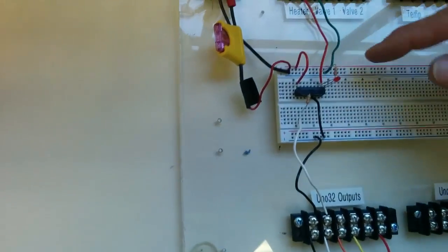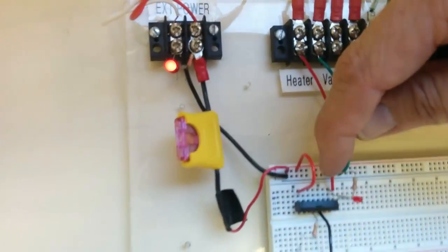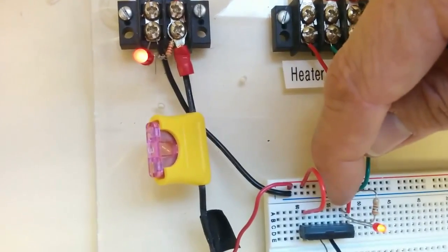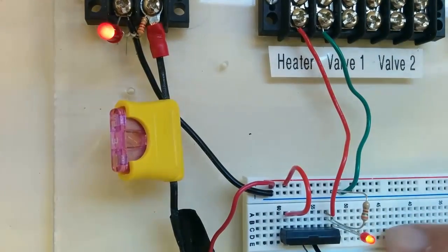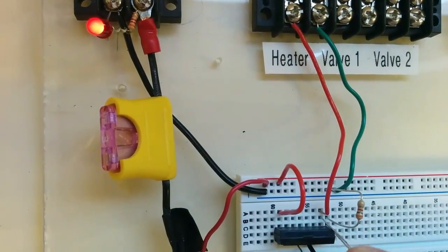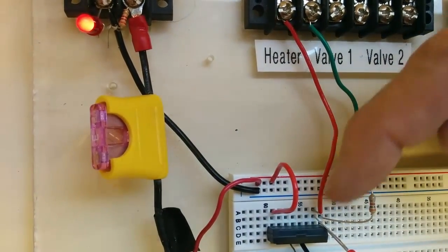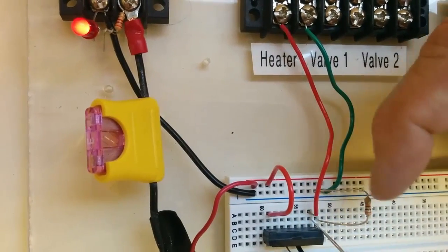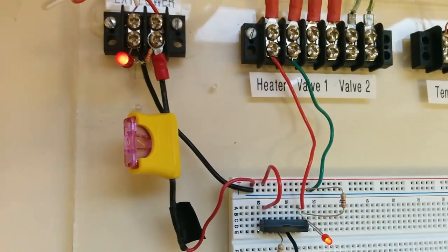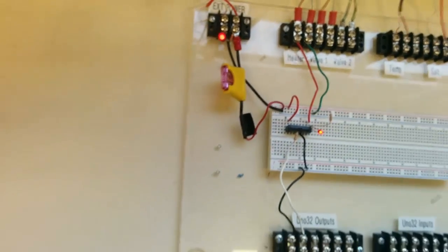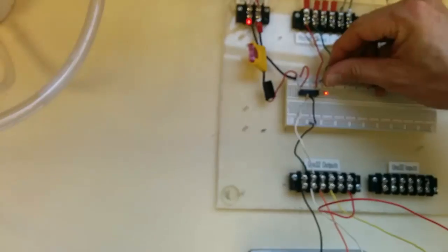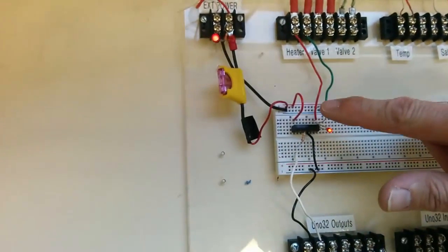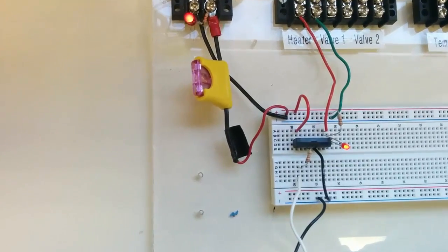All right, so we did have a wiring problem. It's easy to get it off. We were on what would be pin 6, which is vacant. We had to move it over one where the LED comes out. I'll bend this back just a little bit, bend this one over. So we went from 7 out through the LED and then over to ground. And the program we've got running turns on the digital output for 8 seconds and then turns it off for 1 second. So you'll be repeating this in class, selecting this resistor, and we should be ready to go.